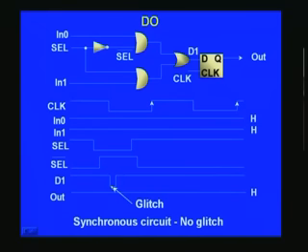Now if you process this elsewhere without the flip flop, what will happen? It may so happen when your circuit is sampling, it may sample at this point, and that is not the desired point. You wish to sample only when the actual D1 is high, but you might sample here without your knowledge. So that will play havoc. Had you given this as a clock input for some other circuit, I don't have to tell what the implication would be, and therefore it is very essential that we get rid of this glitch at all costs.